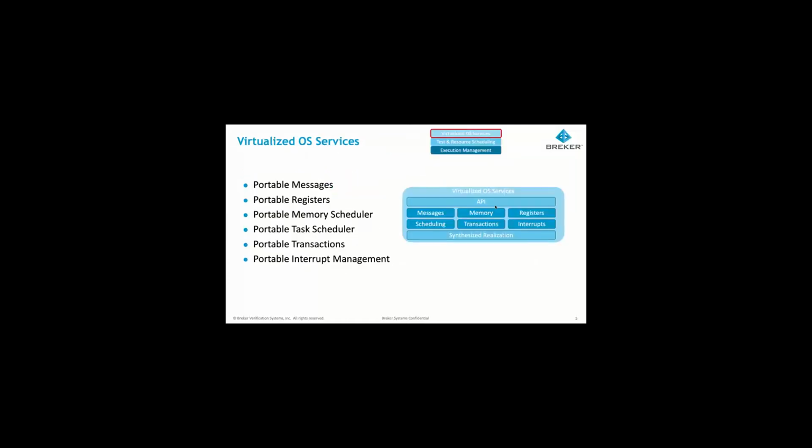What are the virtualized verification services we require? Well, the idea here is that if we're using a language such as portable stimulus or C++, we need to be able to provide a number of different mechanisms that are common regardless of which part of the verification process you're looking at. So maybe the SoC level and UVM. You need to be able to perform such things as memory allocation, as Nick just mentioned, have common register maps, common transaction forms, and so on, and make sure these are portable across all these different phases of the